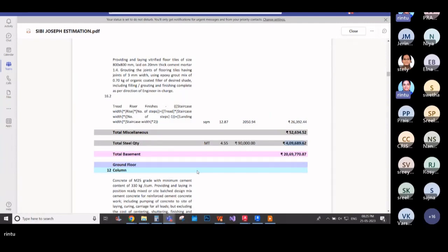And for wise use of bar, you will have to control how it is cut, how it is bent, and how efficiently it is arranged. From the design side to the implementation side, everything must be checked so that wastage of steel by over reinforcing and by cutting is avoided. So that is a very important part.